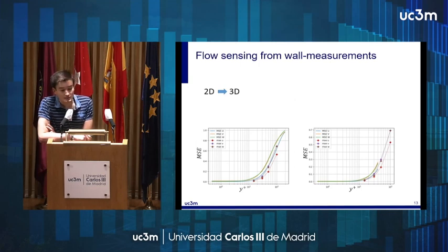As you can see, after some distance from the wall, the error is larger, and it doesn't mean that it is predicting badly. The thing is that it is not predicting, and it is because small scales cannot be predicted accurately from data from the wall for physical reasons, not because the network is doing its job badly.